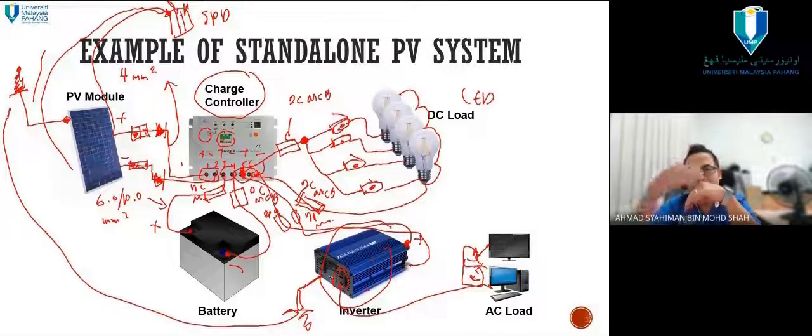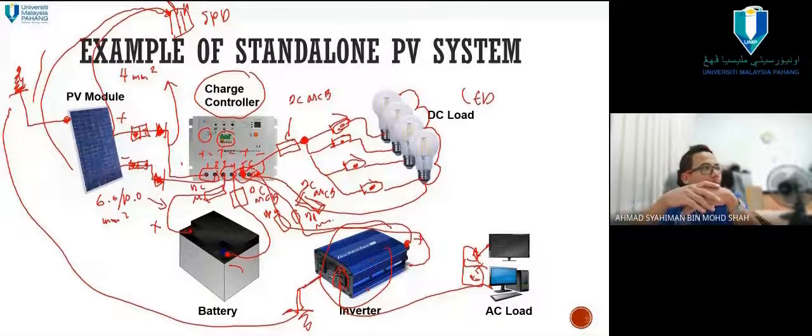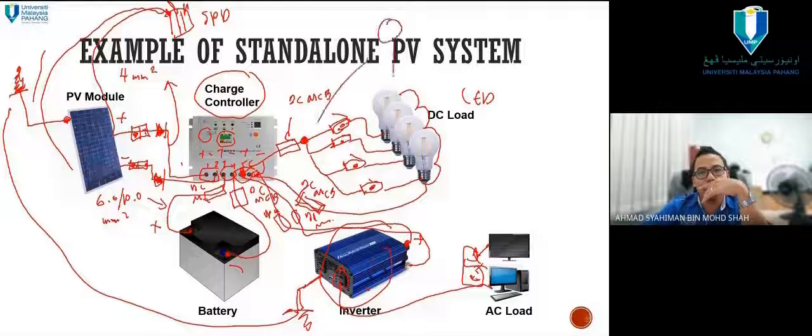Okay. Then you can check lah the fuse, the DC MCB, the SPD, surge protection device, DC miniature circuit breaker, all that things you need to check it. So that make sure if you want to plan, itulah macam saya cakap tadi, sometimes you can put the DC fan. Recently we had the DC fan.